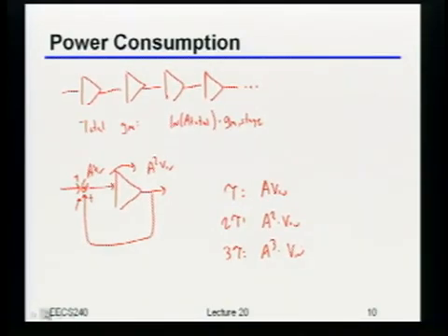So in other words, what I'm really doing here is I've just taken this long chain of amplifiers and wrapped them on top of each other, right? So now, why is this really good news? What's the great thing about this, which I set up to begin with? I only need 1 GM, right? My total GM is just that 1 GM. That's pretty cool, right? Because now I can actually get these ridiculous gain bandwidths we were just talking about using only just that one stage, right?